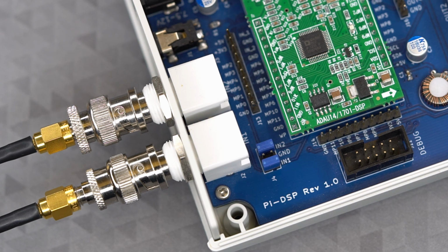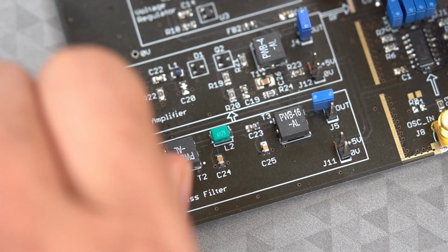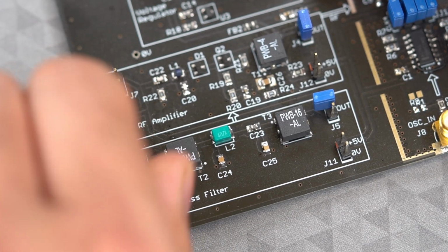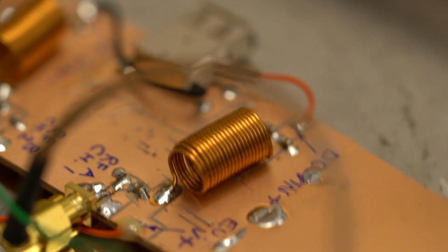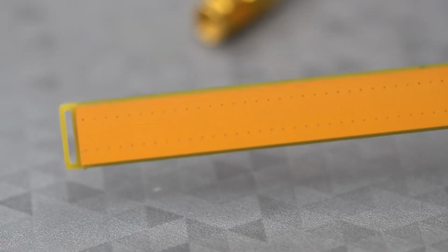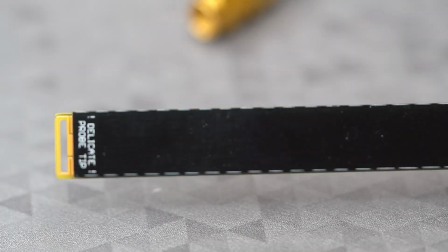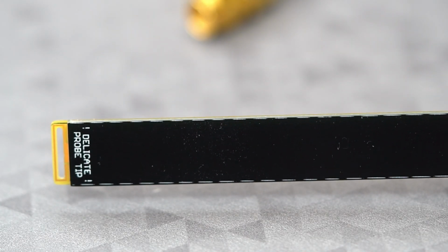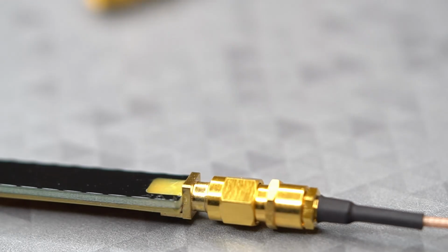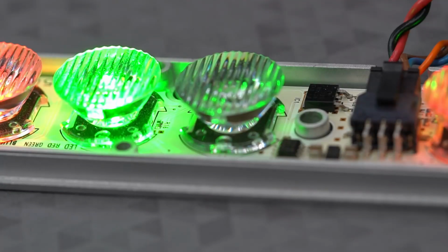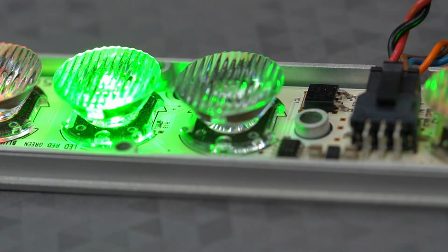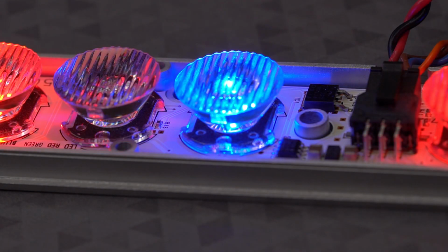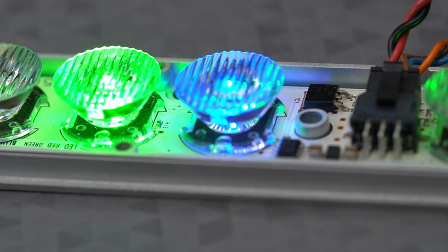The spectral analysis is intended for seeing signals with more insight and detail than would be possible with a time domain view. So this should suit things such as examining filters and oscillators and for minimizing distortion in systems, but also particularly if you're developing new hardware and wish to test for electromagnetic compatibility during the development process. If you're developing firmware, then the MXO4 should be usable for examining data buses, working with memory devices, and also onboard high-speed or off-board industrial protocols, even when there are large data streams containing thousands of bytes being transferred, since the instrument has a lot of sample memory.